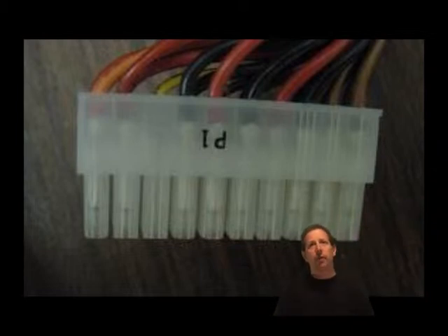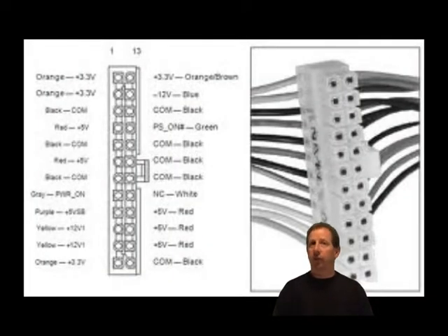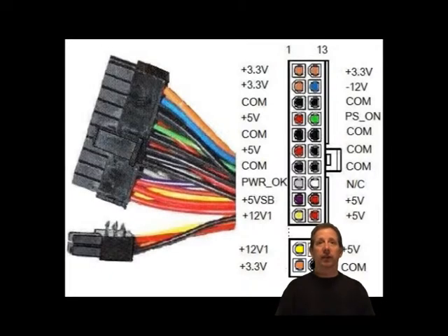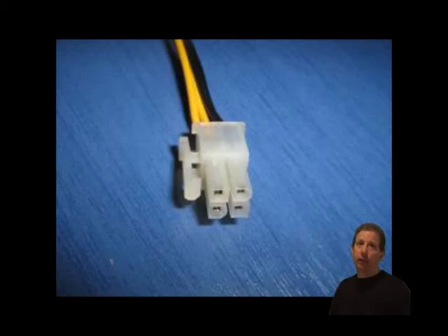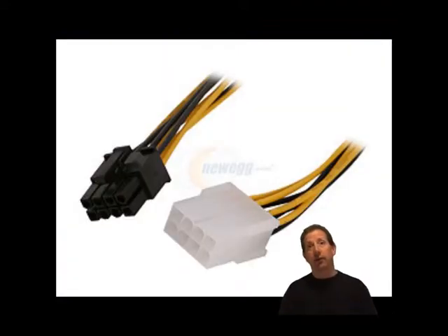The electrical requirements for motherboards changed over time as new technologies made additional demands for power. When processors began to require more power, the ATX version 2.1 specifications added a 4-pin auxiliary connector near the processor socket to provide an additional 12 volts of power. A power supply that provides this 4-pin 12 volt power connector is called an ATX 12 volt power supply. Later boards changed the 4-pin 12 volt power connector to an 8-pin connector that provided more amps for the processor.